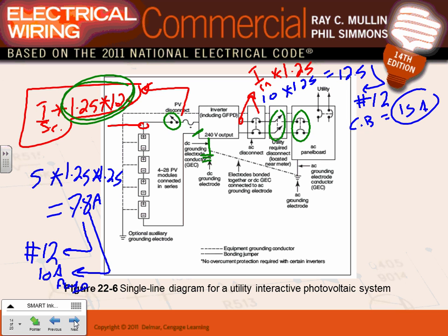The negative is grounded. And then the AC system is also grounded, and you need to tie the two together. Can you guys see that? How to tie them together? Typically, all these systems have to be all bonded, tied. When I say tied, bonded. Typically, minimum number 6 AWG, and this one is typically number 6 AWG.